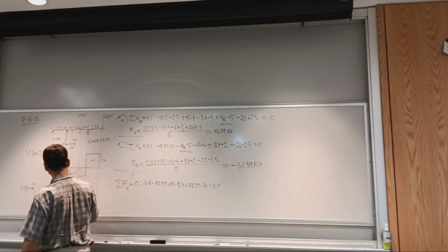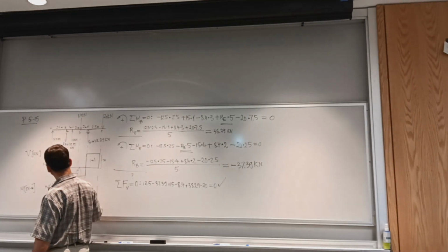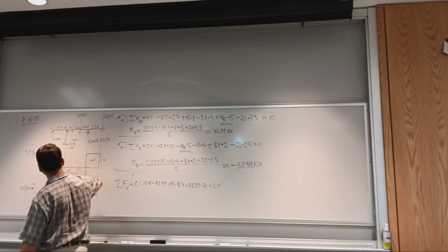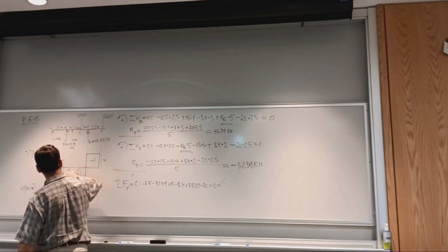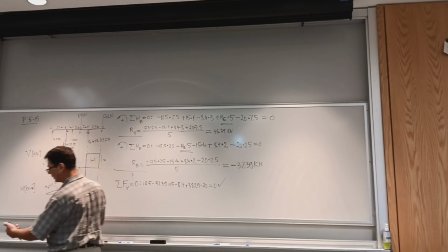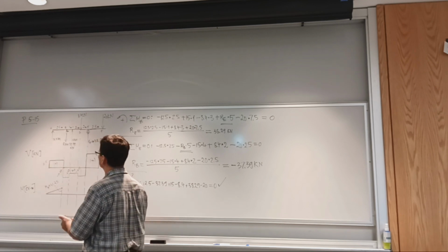So in order to draw the line, I need to know where to stop, right? So to get it, I need to evaluate the moment at point C. I have this area. I'm subtracting, because it's negative, this area. Again, this shows that the whole thing is negative. Okay, so I already have 31.25 positive, and I'm going to subtract 24.89 times 1.